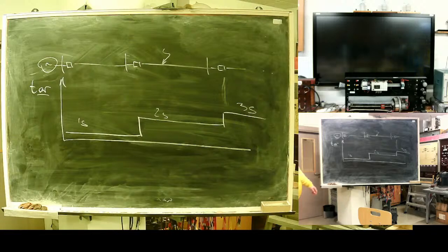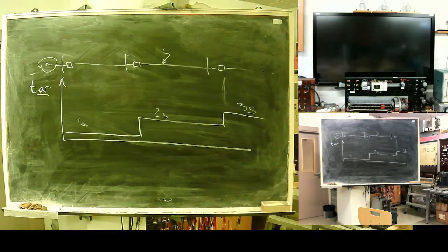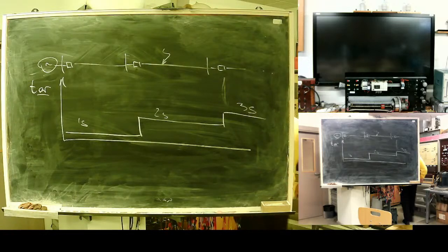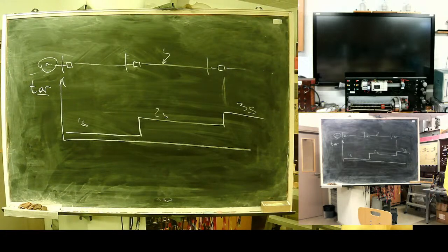Also, one more thing. Not always. In general, most will. For example, this tiny guy. It's a 24 kV switch. Then we disconnect. See? It has enough energy in its spring for a full cycle. Disconnect, reclosing, disconnect. Now the spring energy is depleted. I need to get it back online. Now it will recharge. Yeah, spring recharge. Ready to operate.